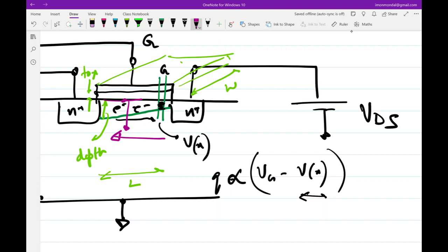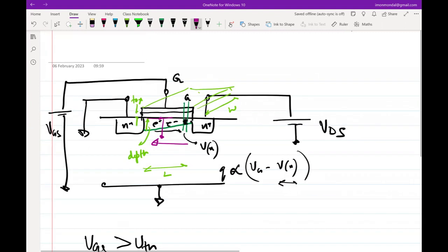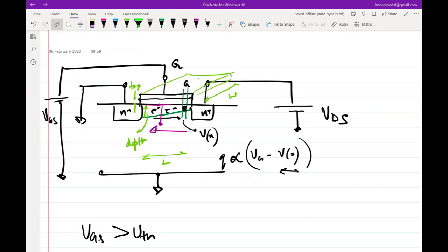Now, if you put a microscope and observe that sheet of charge, there will be a profile. But that profile is not of too much consequence for circuit designers. If you are a device designer, for the same structure, if you are making this device, then the parameters in your control, everything that you see here, you can change: the doping concentration, the thickness of the oxide, the N plus doping, and obviously WL.